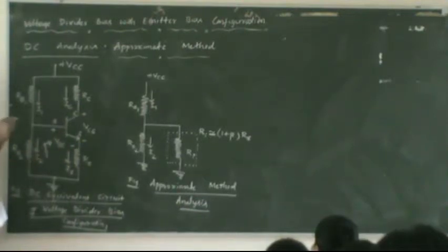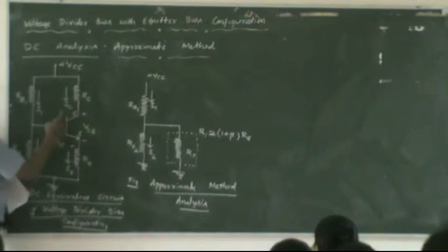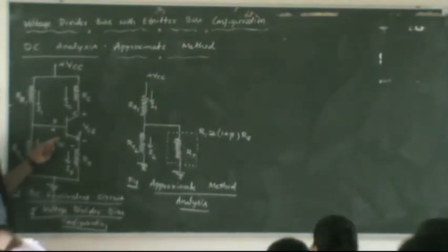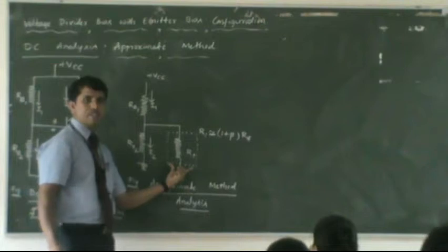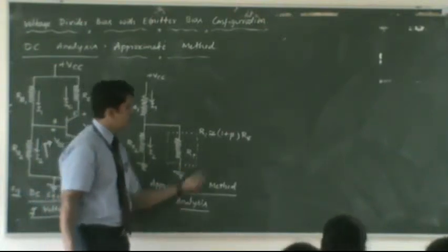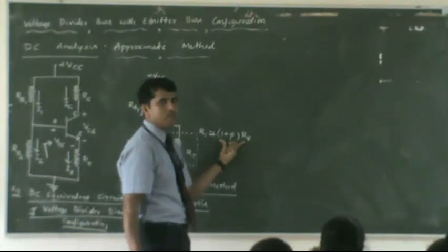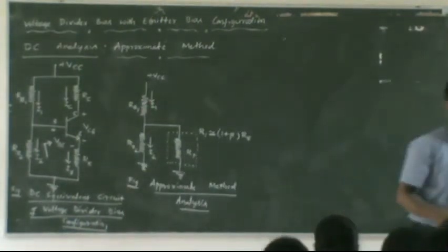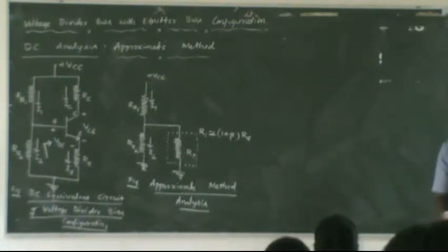Normally, for the current flow, whether it's medium resistance or large resistance depends upon the circuit. But here what I am trying to do with the input section, whatever you are seeing from this side, the resistance offered by it is replaced with this resistance. And this resistance RA is nothing but 1 plus beta times RE. Look at the denominator of the IB expression.